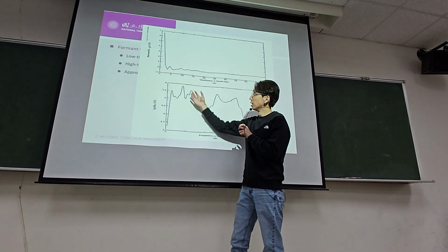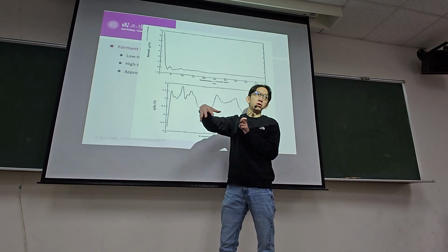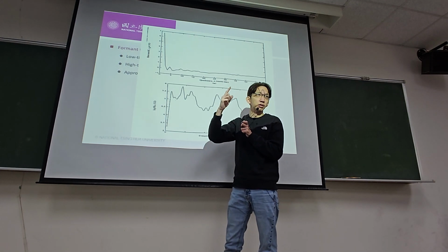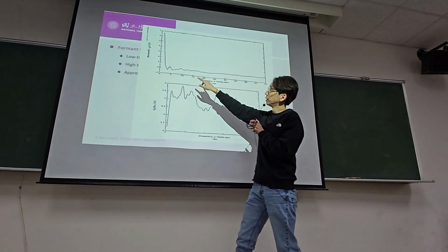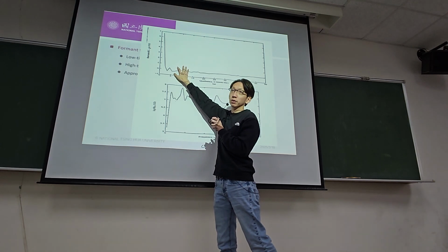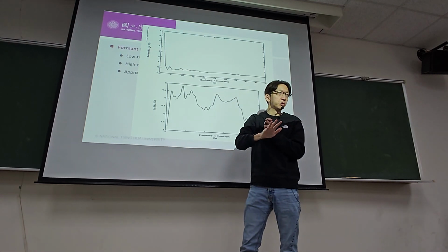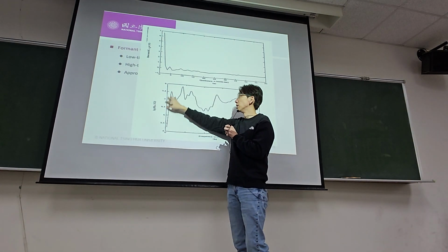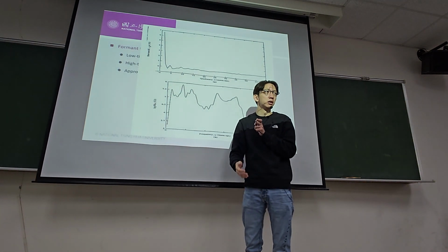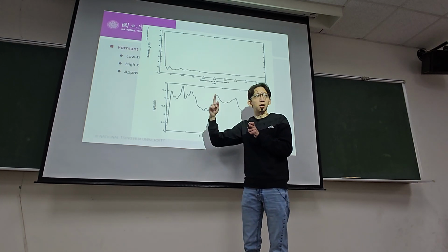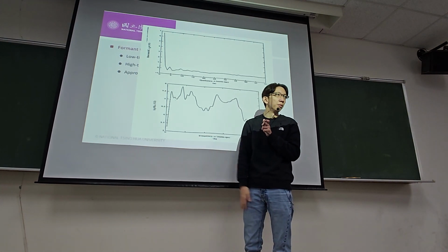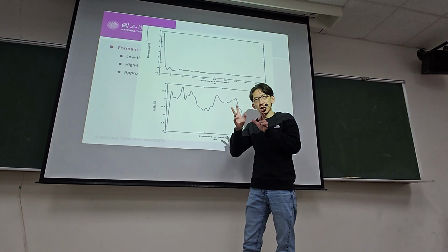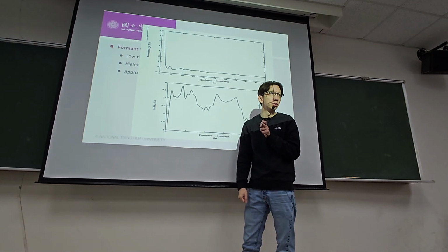So what you can do is take the portion you want into a Fourier transform. Then, if you want to return to the original scale, do an exponential. If you take this low time part of the quefrency and plot its frequency response, it will look something like this: a very smooth spectral envelope related to formants. Those high oscillation points are gone, because the source part has been thrown away. The small portion of low time cepstrum coefficients relates to your filter.